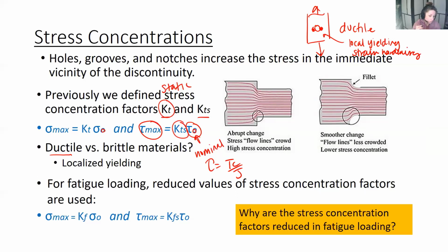So we don't usually apply the stress concentration factor to ductile materials for this reason, but we do account for the reduced geometry. So sigma equals P over A still holds true, obviously, for a ductile material. If you were looking at the max stress, you'd use the reduced area, but you wouldn't necessarily have to tack on the additional Kt to that.